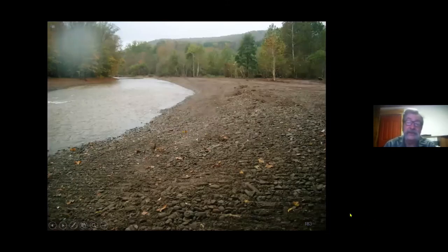And here's the site after they're done. You can see a little bit of the roots sticking out right here where they buried that. They did a nice job of fine grading that. What they need to do is get some vegetation on there, whether it's planting some trees or putting some seed mix down, so that they get a quick cover to hold that really fine material in place. But here's an example of where the avulsion went to the right of our picture. It's now filled in, and we buried some of that wood to provide extra reinforcement to secure that bank.